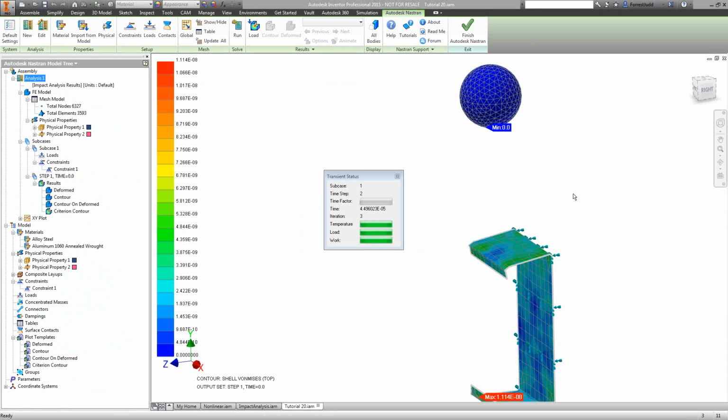So this is all automatically determining the optimum time step, and ultimately a lot of the tricky things that you might have to otherwise specify, like how long does the ball take to get down to the bracket, and what should my time step be to accurately capture everything that's going on. It sort of just figured all that out for us.